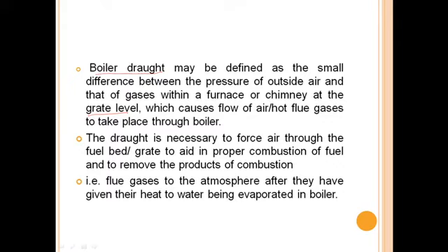Basically, this draught is necessary to force the air through the fuel grate to aid in the proper combustion of the fuel and to remove the product of this combustion, and the flue gases to the atmosphere after they have given their heat to the water being evaporated in the boiler.